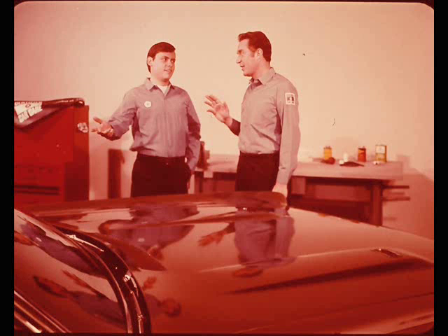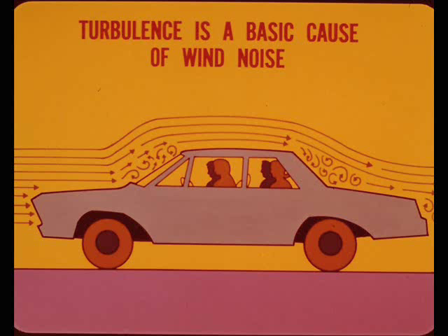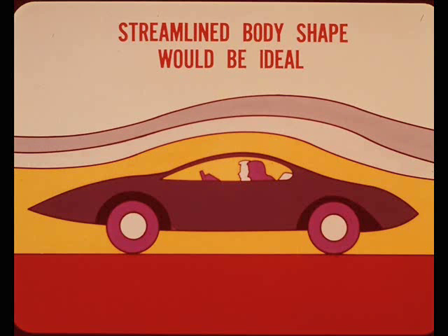Well, before we get into that, you should know something about general causes of wind noise to help you sort out the possible sources. You see, turbulence in the airflow around the car body is a basic cause of wind noise. Generally speaking, turbulence noise can be caused by anything that disturbs smooth airflow. This can be the shape of the body, protruding parts, or loose parts. A fully streamlined body shape would be ideal, but cars are designed to carry people comfortably, so we get some turbulence noise which cannot be avoided. Fortunately, the level of noise from this source is acceptable to most people, provided the body is well sealed.